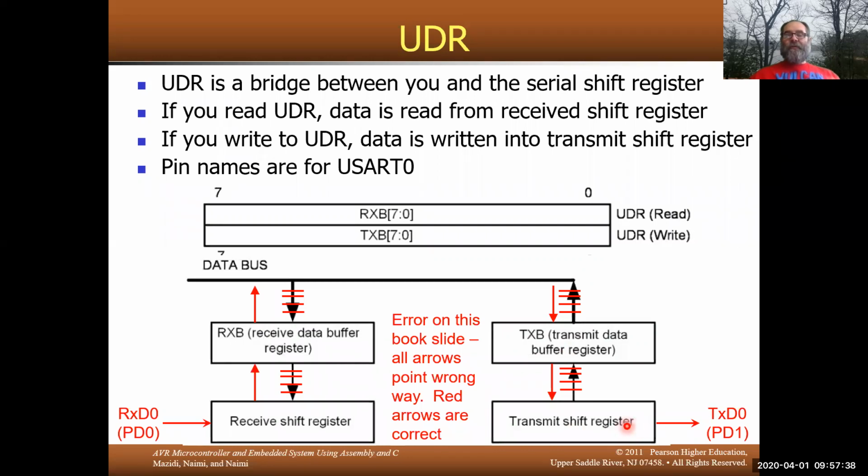To shift out 10 bits, the 8 data bits plus the start plus the stop, takes 100 microseconds or 0.1 milliseconds. So to shift this out is going to take 0.1 milliseconds.